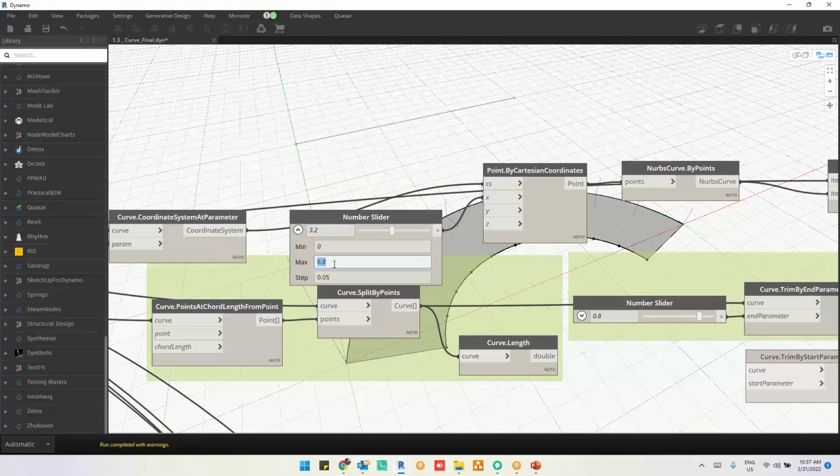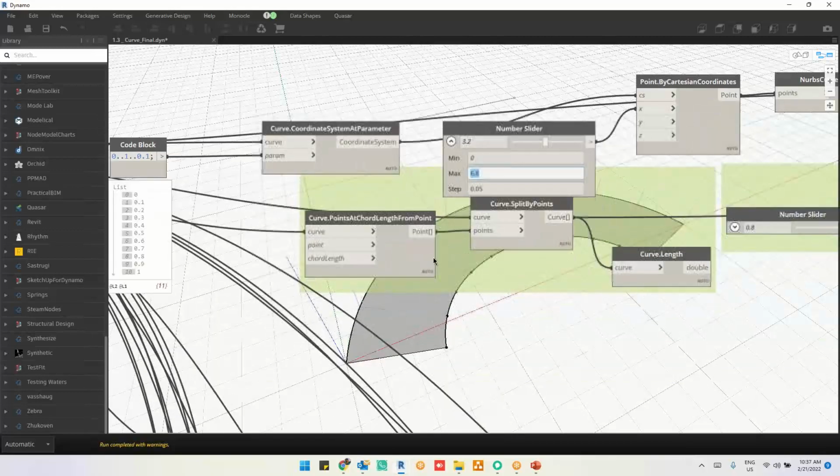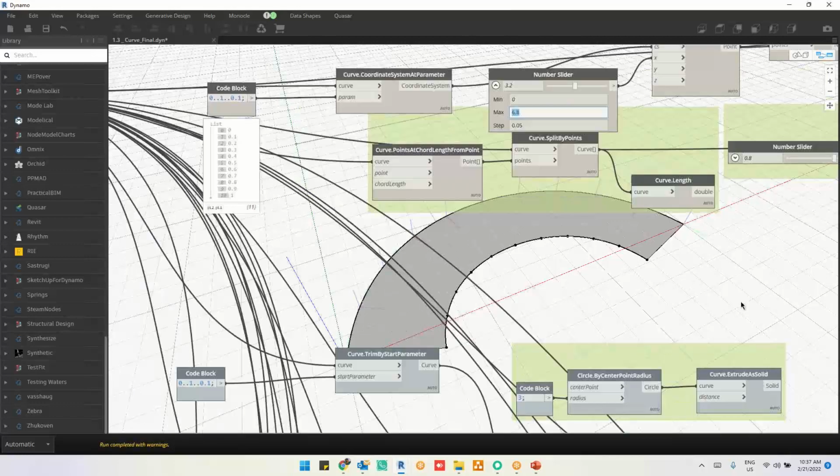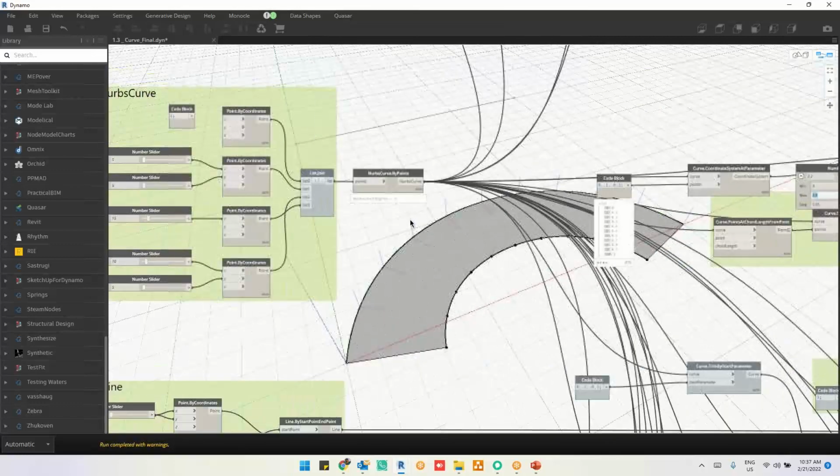Say I want this to go up to 7.5 because my road width is 7.5 meters. Then how do I split that? If you can't control it here, you have to control the start point, the start curve. So you have to increase the start curve. I'll be changing the values here. If I change the values here, it will expand and extend the values here as well.